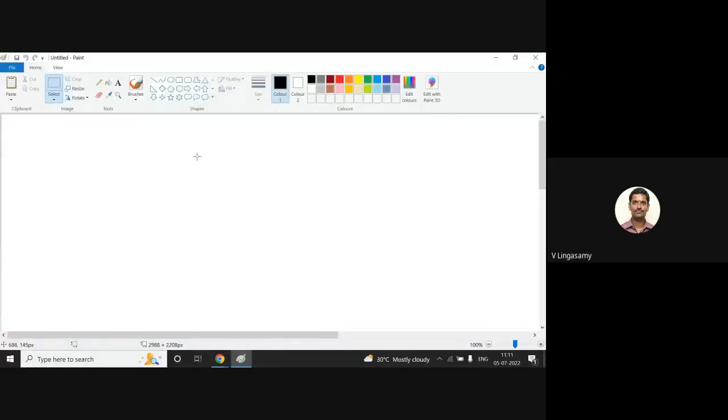For example, see, let me share my screen. I can tell in RF terms as well. Is my screen visible? Yes, sir. Okay, madam. So this is the bandwidth, right? For example, let's say 10 megahertz. I have got a spectrum of 10 megahertz from the regulatory body. Now, how am I going to make use of this entire 10 megahertz? It's not possible because we have to give some kind of guard band, so almost 9 megahertz. But they will even operate only 8 megahertz most of the time.